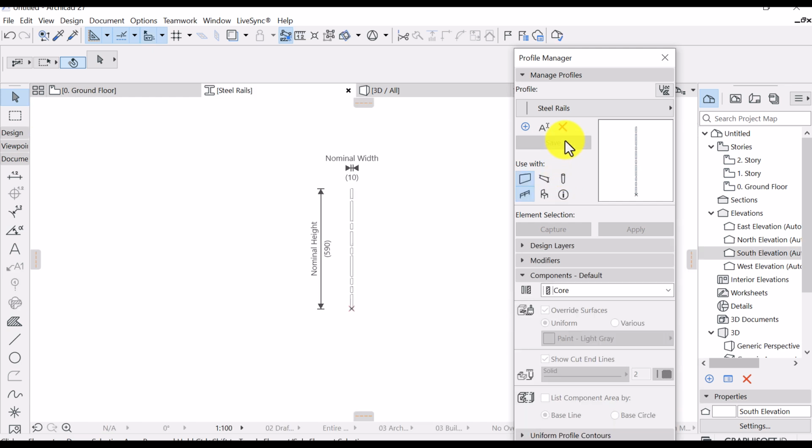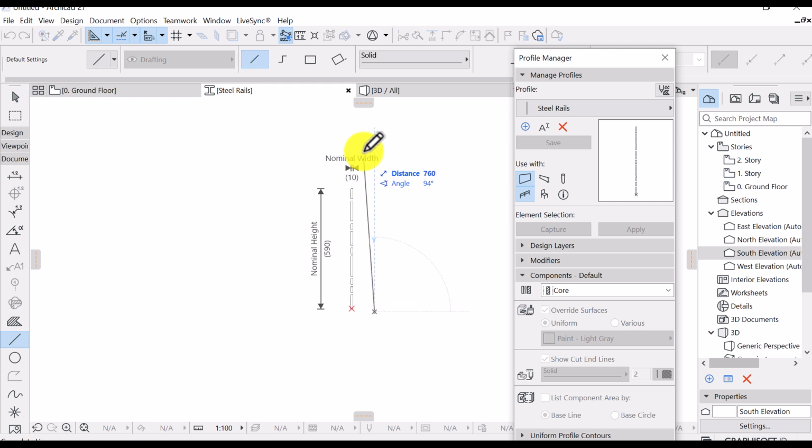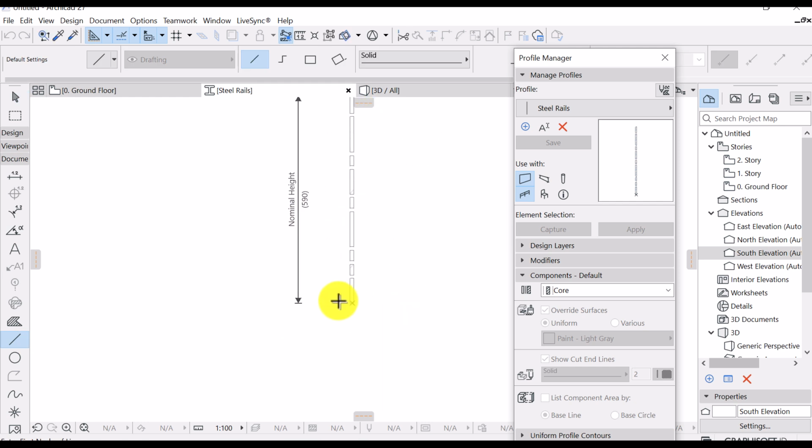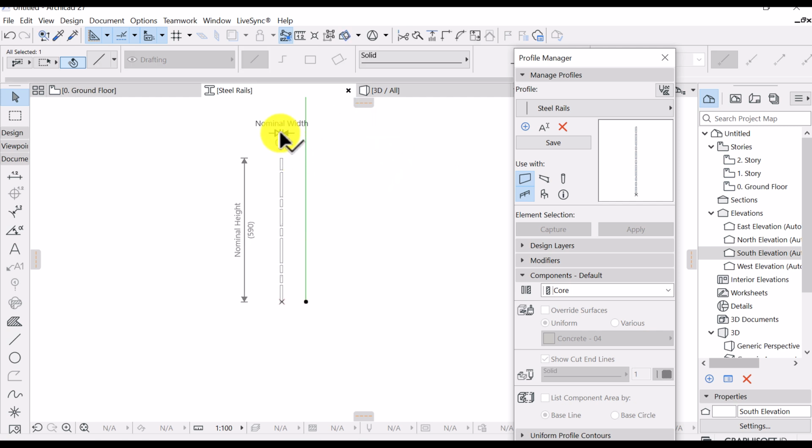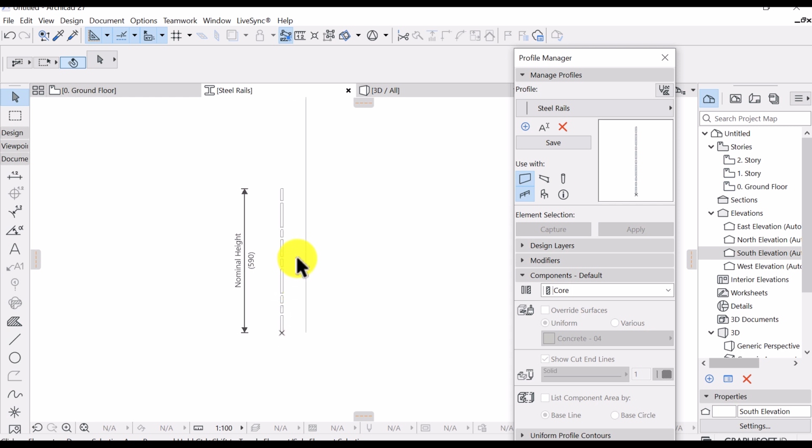So I'm going to go back to our profile, and then I'm going to draw a line of 1.4 from the base, or from the point. 1.4, enter. I'm going to drag this line just outside the elements a bit, and then move this guy up there to clear the space. So we have a challenge of distributing this along that. It's going to be quite a challenge, because they are in different sizes.